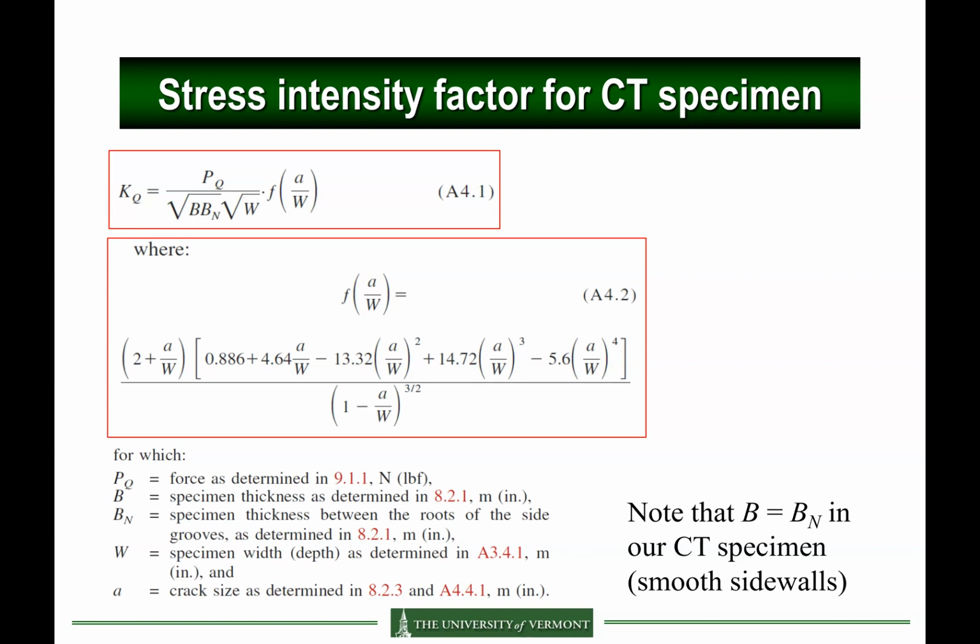Okay, so there's no bifurcation of the crack when it propagates. But usually I don't like this technique because it creates an additional stress concentration on the side. So it's just better to leave the crack grow as it likes, especially if the grain size is large. You'll find that the crack does not propagate flat because the grain is too large. Okay.